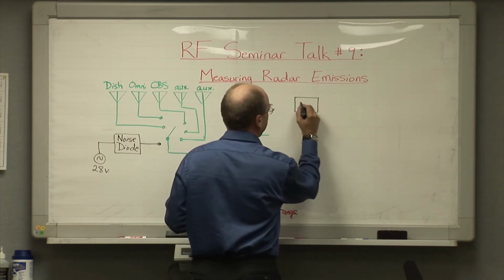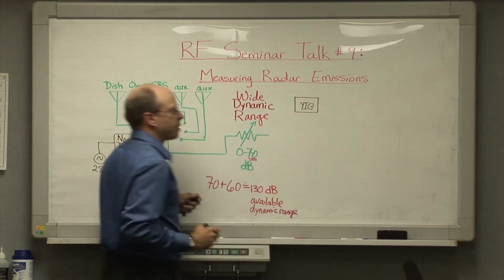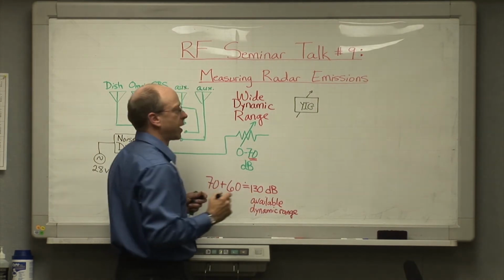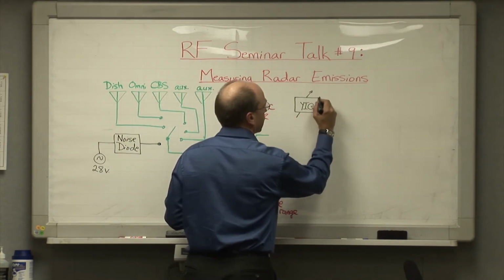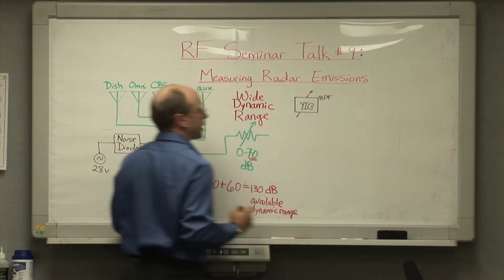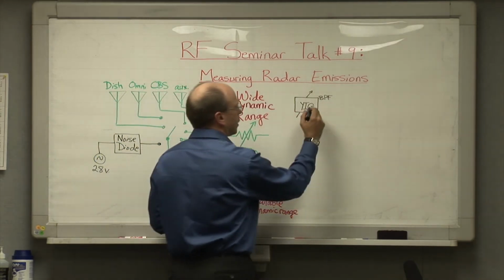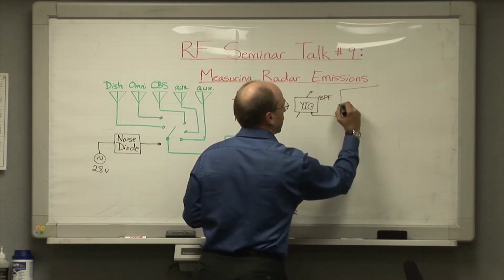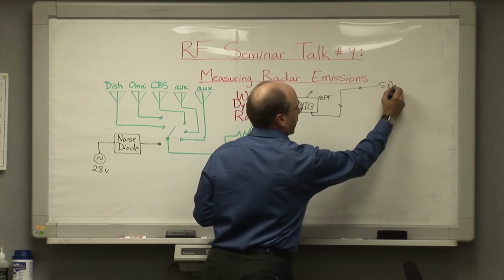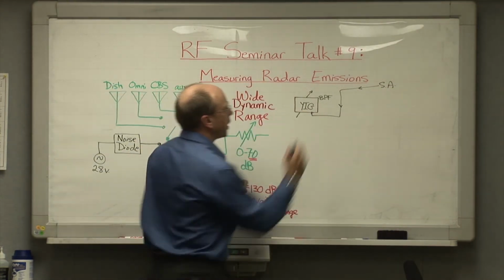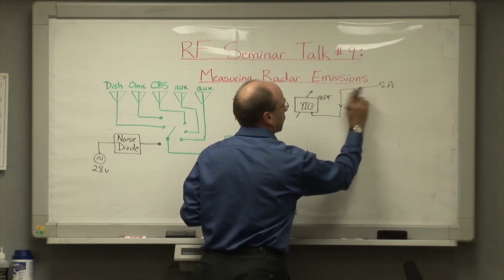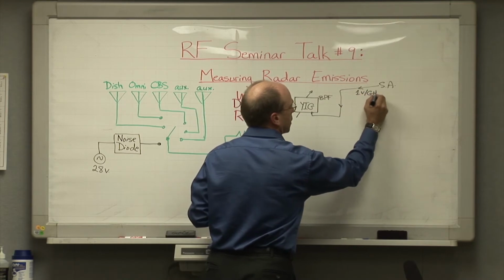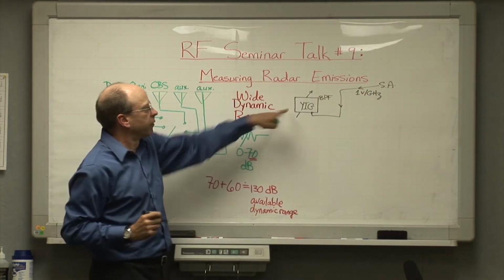filters. We'll have one that's a yttrium iron garnet filter, which is a tunable bandpass filter. In fact, all of these are bandpass filters. We're going to label this BPF for bandpass filter tunable. And remember that the control voltage for this comes in from the spectrum analyzer, so that this knows, based upon a voltage that's something like 1 volt per gigahertz, and it does vary, but something like 1 volt per gigahertz, what its tune frequency needs to be.